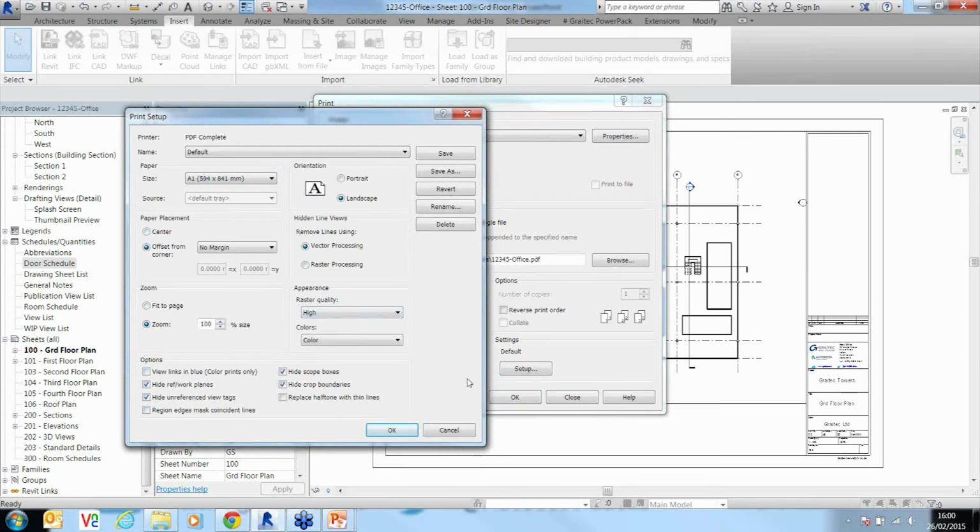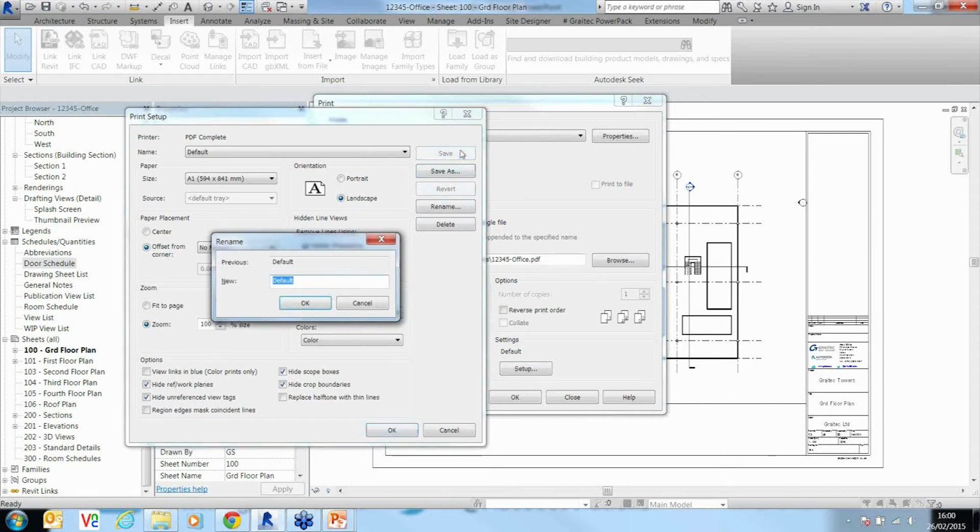Okay, we don't have CTBs or STBs in here, so if you draw something and put color to it, it will print color. You don't have to set the line weights because obviously they're set in the background for each element. So for example, you define the thickness of the line weights for each element itself, as in wall, door, window, floor slab, beam, column, etc. Just all inside here. So when you print, it prints out exactly how you wanted it to, rather than having to change the colors.